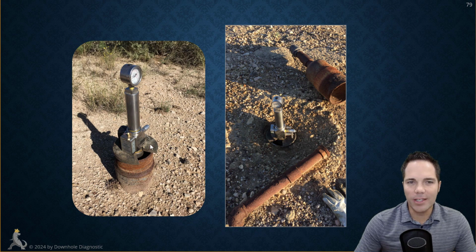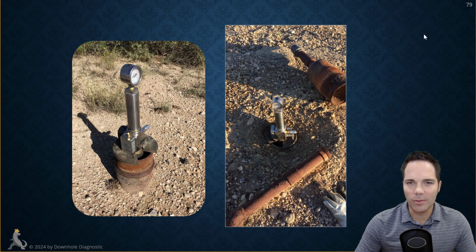Anyways, I found this tubing wiping rubber that my fluid level gun is sitting on. This is something used on a pulling unit to wipe the outside of the tubing to make it clean. I found this on one of the locations, and I started sitting my gun on top of it and taking fluid level shots, and it actually worked. It helped to centralize the focus of the energy back enough to the microphone to detect where the fluid level was. And I made a little video of this one right here.